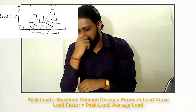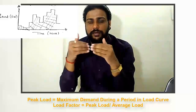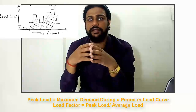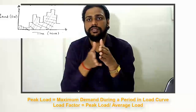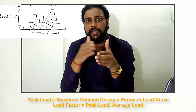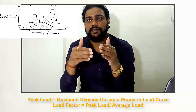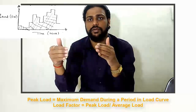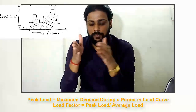And again, there is a capacity factor, which is the average load divided by the plant capacity. The plant capacity is the maximum which the plant will be able to produce if it is loaded fully. So in the example I gave, my average load was close to 1400 and my connected load was close to 2000, so 1400 divided by 2000 would be my capacity factor.